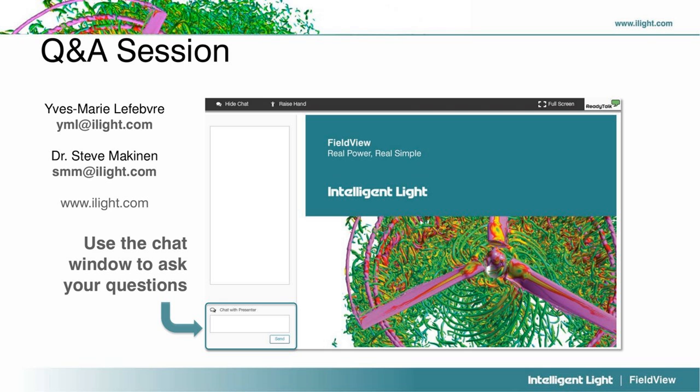If you were to save the full results over time, some customers do that, you could run FieldView in batch. Each time a time step is saved, you could process that, generate the extract in batch, and work from the extract. So there are several options before a full in situ instrumentation that are possible. And I'm sure I mentioned it, but the export from OpenFOAM will typically be in VTK format, and of course there's a VTK reader in FieldView.